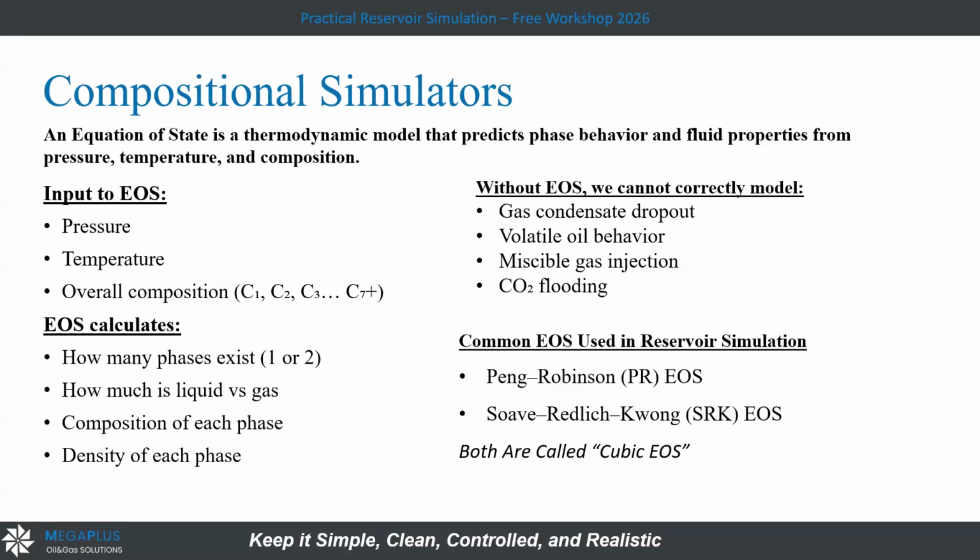So the equation of state, what is the equation of state? It's a function, or an equation, that you can go and look for, but I can help you with the two most popular equations: the Peng-Robinson equation and the Soave-Redlich-Kwong, the SRK equation of state, called the cubic equations of state.